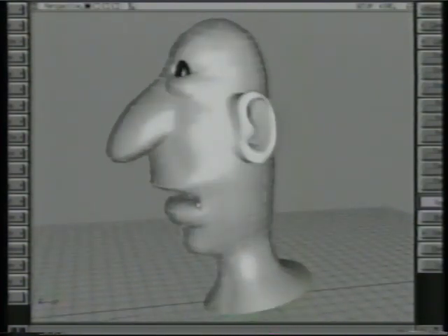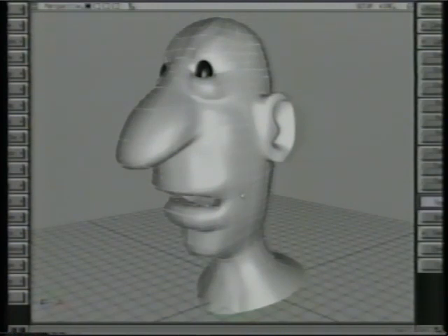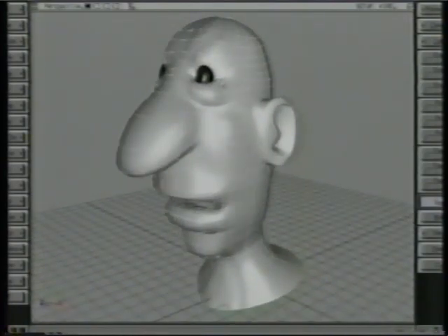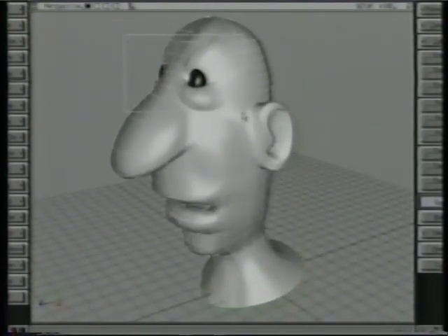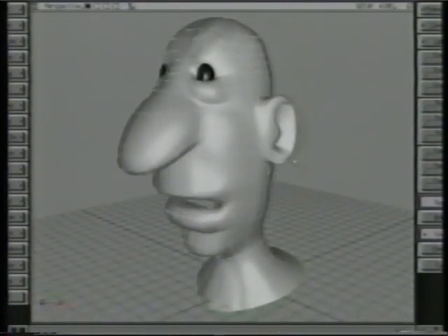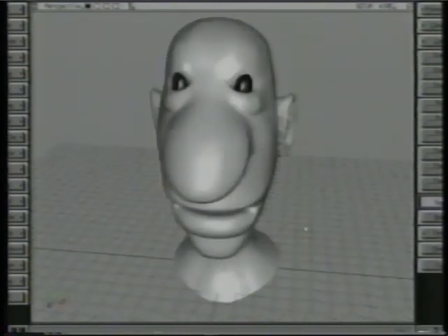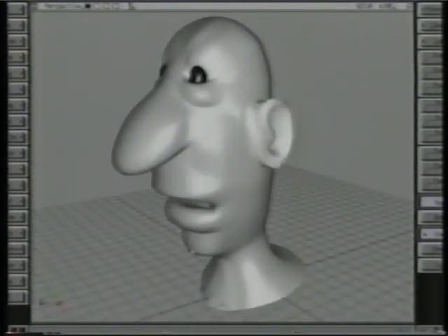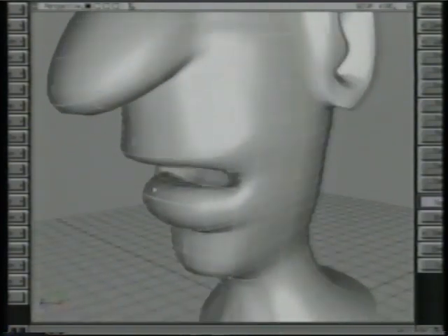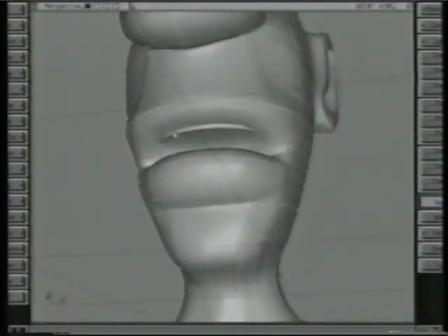The way to make the mouth, again, with this sort of character, is to increase the resolution right around the corners of the mouth, so you can go inside the mouth. Same thing with the eyes. This has very simple eyelids, so it required very few lines. It's very simple shapes. The ear is connected on afterwards. We'll look at those surface connection techniques in a little bit. The inside of the mouth doesn't have a lot of definition, so in order to do that you'd have to add several more curves, which is an option.